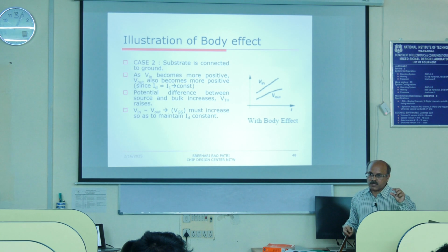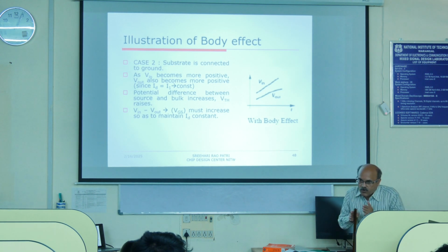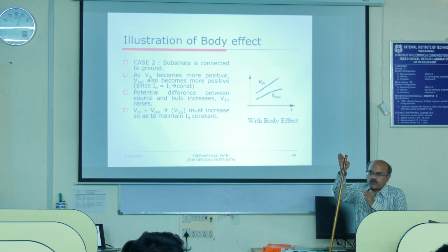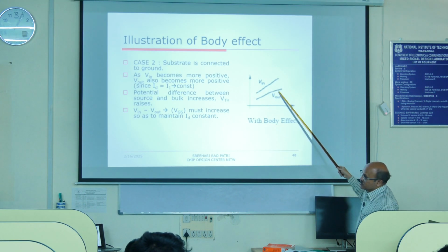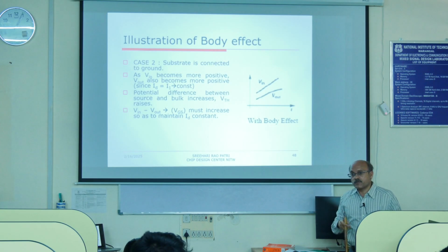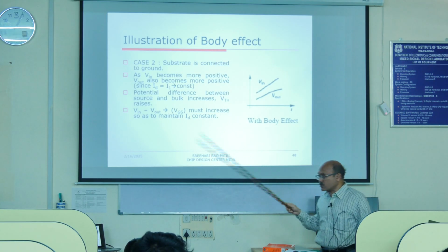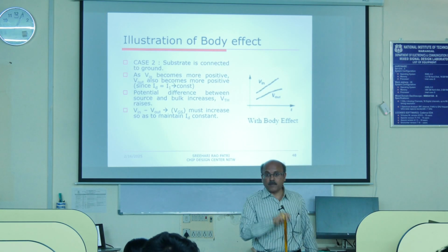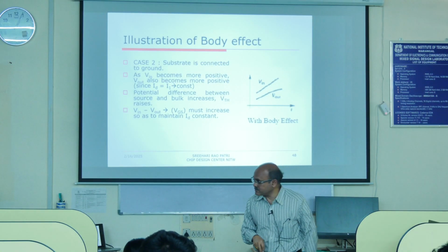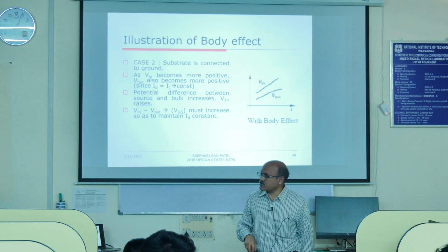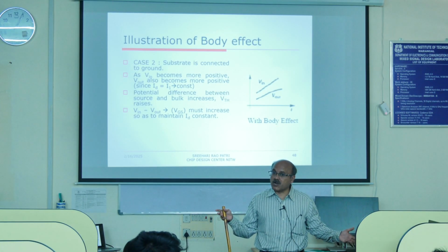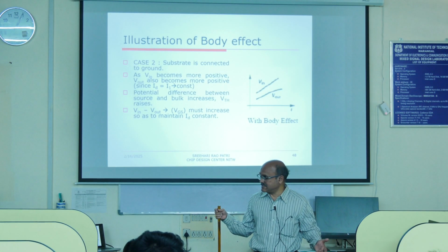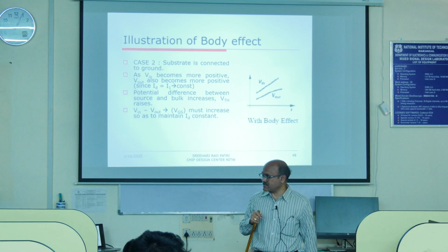Always the difference is threshold voltage. If threshold voltage is constant, the output keeps on following the input voltage. But since the threshold voltage is increasing, that gap also keeps on widening, right? If you use that circuit as a source follower, and if you ignore the body bias effect, then you are in soup, right? You are thinking that the output is simply following the input voltage, but it is not happening exactly because of the body bias effect, right?